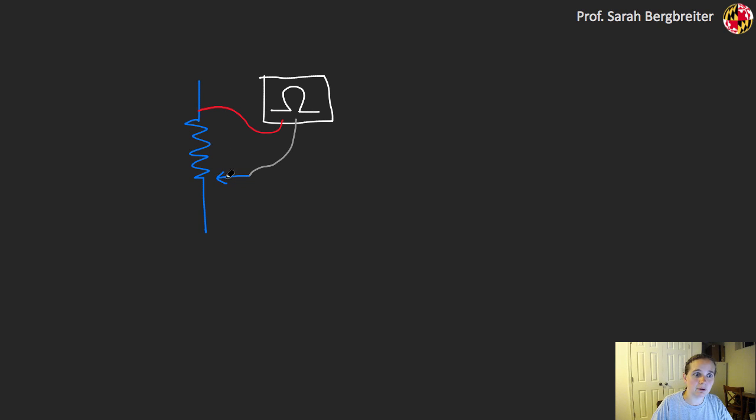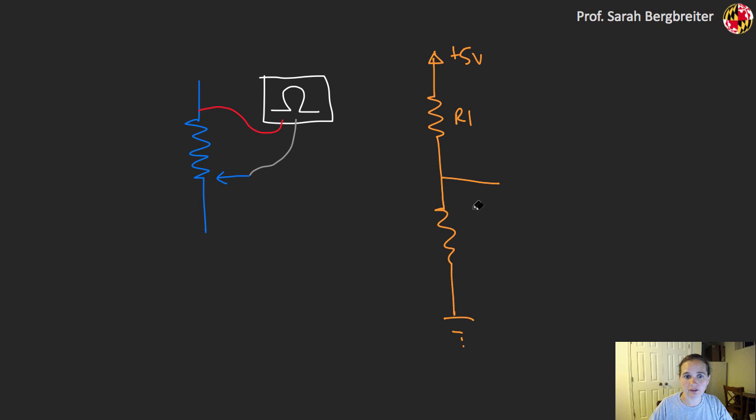And obviously I can measure resistance anywhere in between as well, so I can think of this as a voltage divider of sorts. I can set up my potentiometer like this voltage divider, where I have one resistance here and another resistance here, and those resistances are going to depend on the current position of the wiper. As I'm turning that potentiometer, I'll change that wiper position.